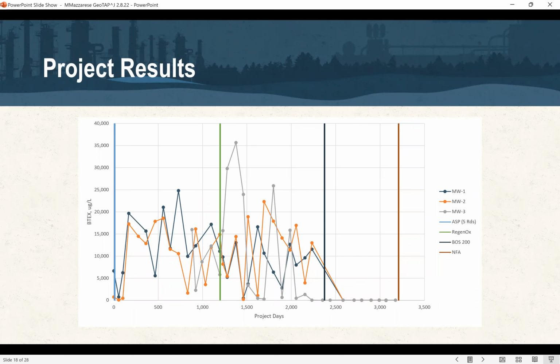And so I think, as on most of our sites, and this one falls into that, obviously it comes down to distribution. When you have these challenging geologies, using wells, so for example, on this site where you've got injection wells, they couldn't get direct push past the gravel, so they're using a combination of direct push and wells to be able to deliver the oxidants, and it just could not get it properly distributed.